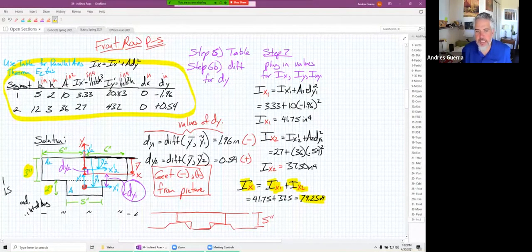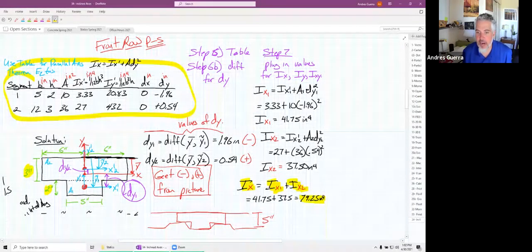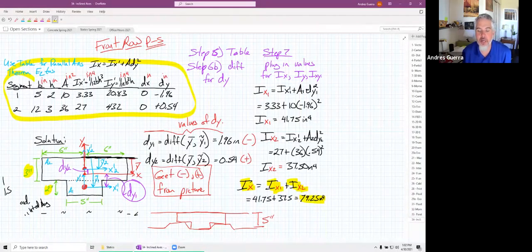By doing this T shape, the equivalent volume of concrete is that of a 4-inch slab. And concrete is not very environmentally friendly. It emits tons of carbon into the atmosphere when you're producing concrete. So if we can reduce the volume of concrete from 5 inches down to an effective 4-inch slab, we're reducing the volume by about 20%. That's a significant savings, right?